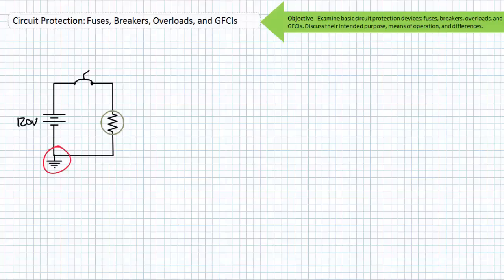If a conductor servicing the electrical innards of the machine accidentally made contact with a conductive frame, the frame would now also be energized. If the frame did not have a return path to the source, let's say because it's sitting on rubber feet or an insulating pad, it's sitting there like a snake, coiled and waiting, ready to bite the next person that touches it, because that person is now a return path. In effect, this unfortunate person, by touching ground, is closing a switch in parallel to the electrical device and completing a path from positive to negative. This is unintentional grounding and to be avoided.